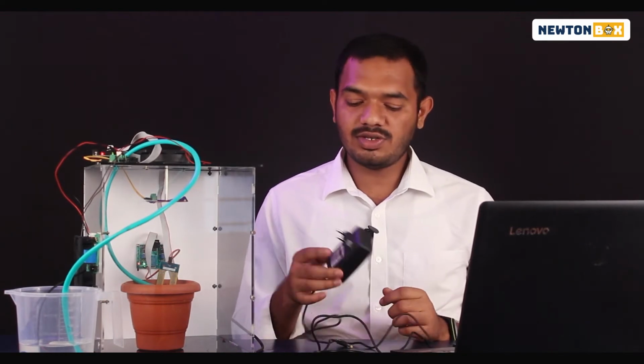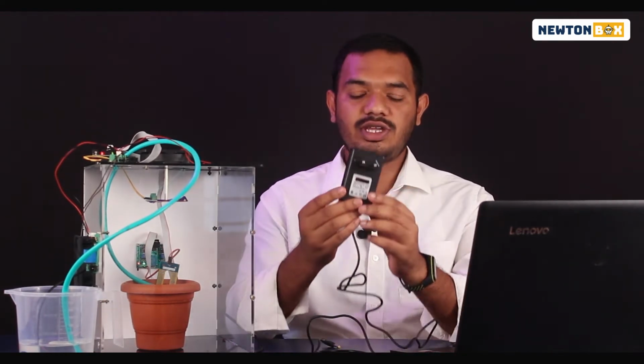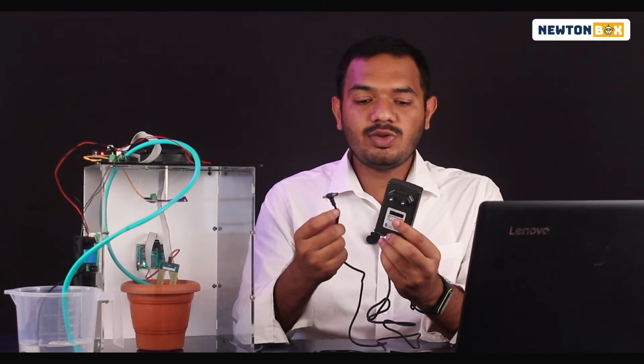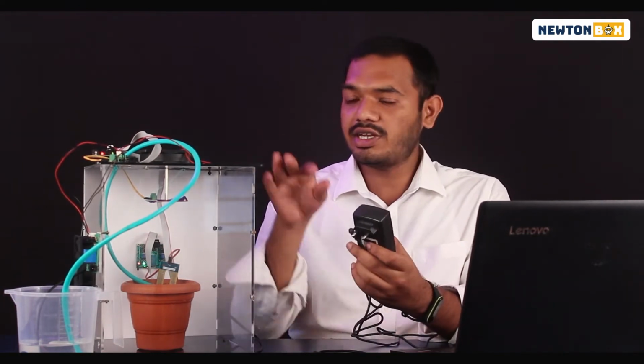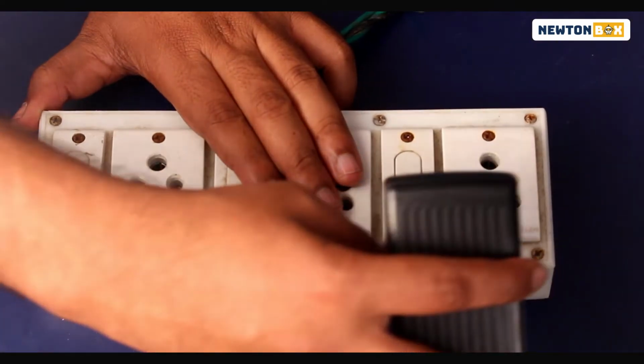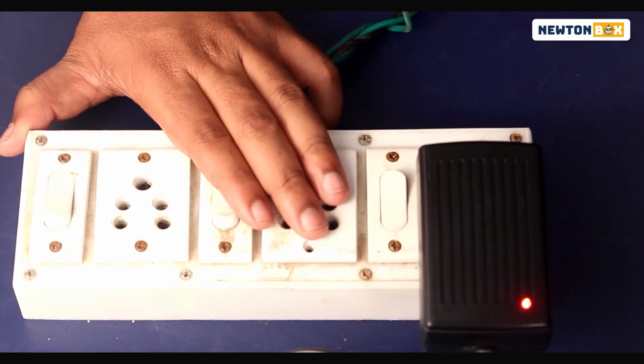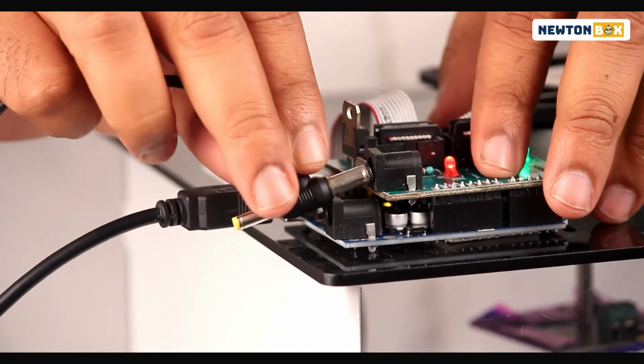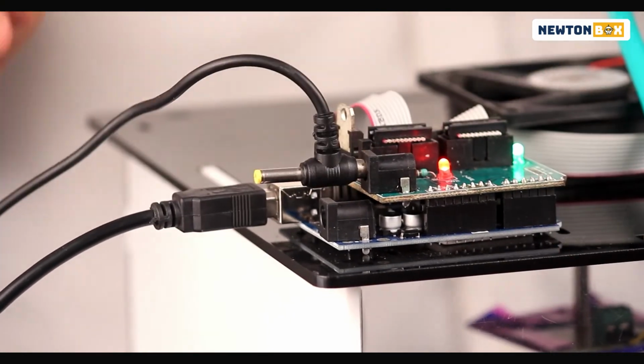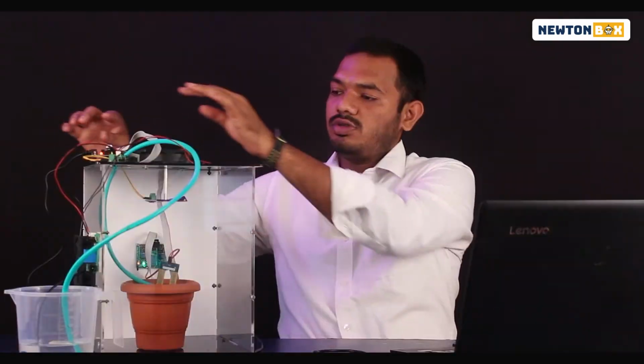Once the program is uploaded, you're going to require another component which is known as the adapter. You can find this in your kit. This is what we're going to connect to the shield for the power supply for the entire automated greenhouse. You're going to connect one end to a power supply. On the other end, this big connector, you're going to insert directly into the automated greenhouse on the shield. So please don't connect it to the Arduino, please connect it to the shield.